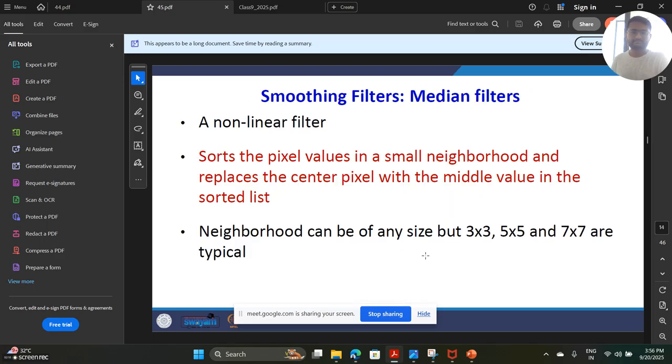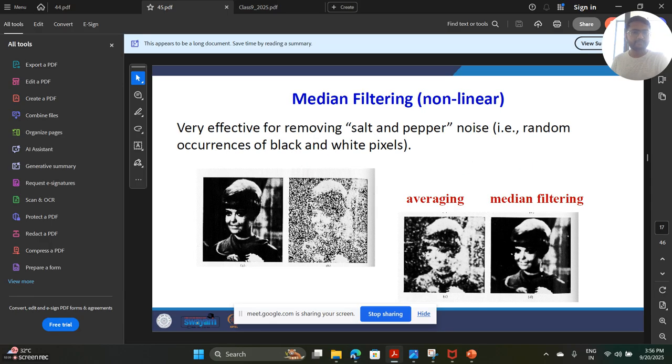Okay, similarly here. First of all, median filters are there, which will remove this salt and pepper noise. The first application of low pass filter is the removal of salt and pepper noise. And this noise is coming in satellite imageries. In satellite imageries, if one sensor or one particular part where it is sensing the signals is not that correct, it will provide the salt and pepper effect. And to remove that in satellite images, we use this median filter.